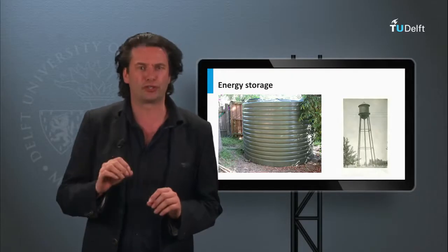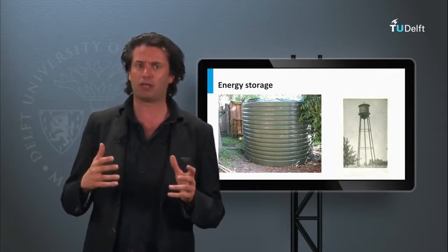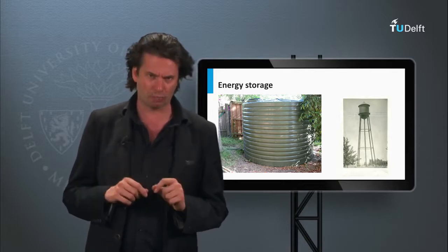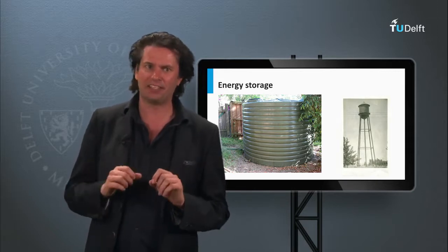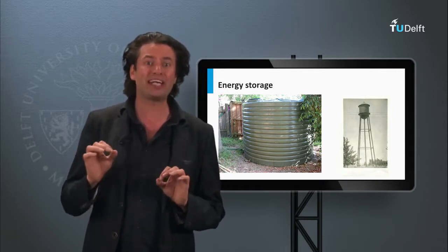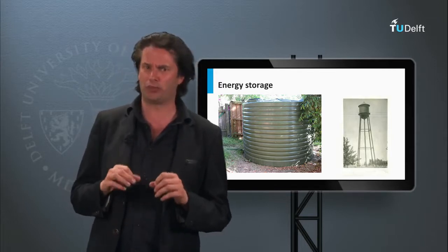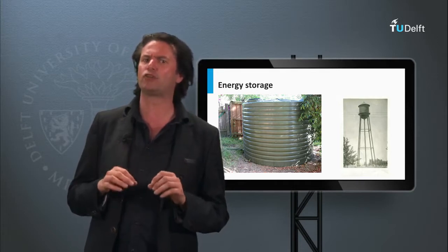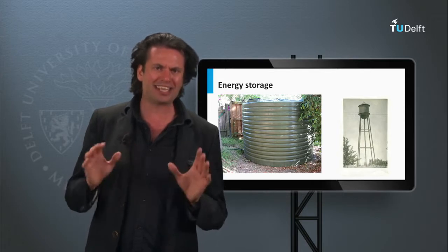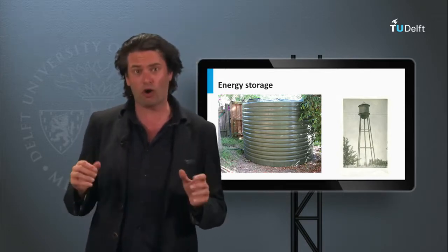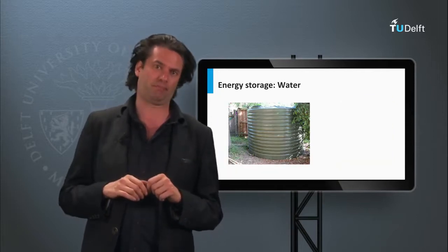Storage has mainly two functions: improvement of the utilization of the collected solar energy, providing thermal capacitance to minimize the load mismatch, and improvement of the system efficiency by preventing the array heat transfer fluid from quickly reaching high temperatures. There are several storage technologies that can be used, and some of them can even be combined to cover daily and seasonal fluctuations. Generally, solar energy can be stored in liquids, solids or phase change materials, abbreviated as PCM.